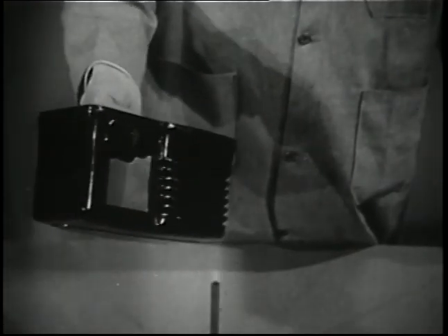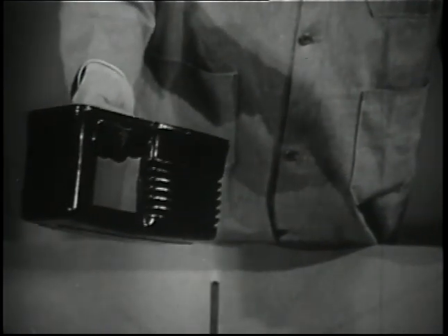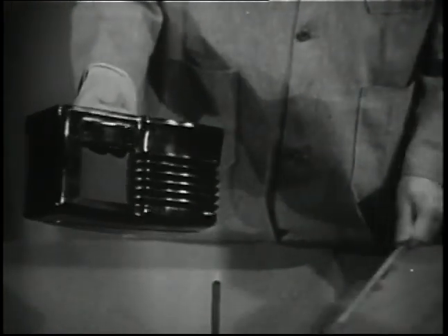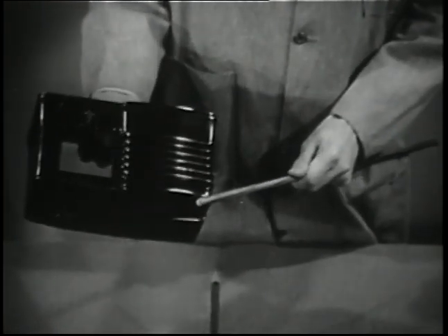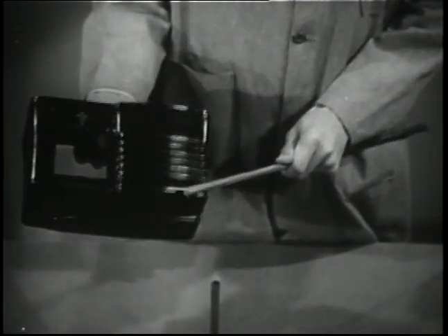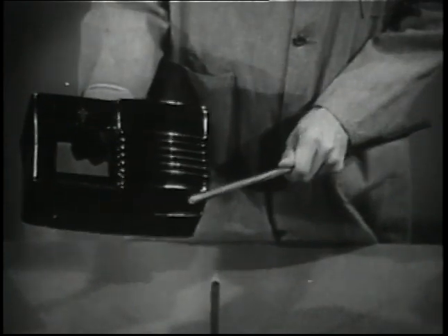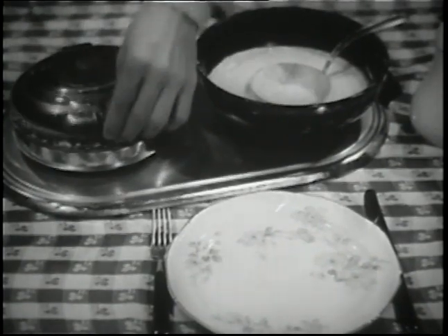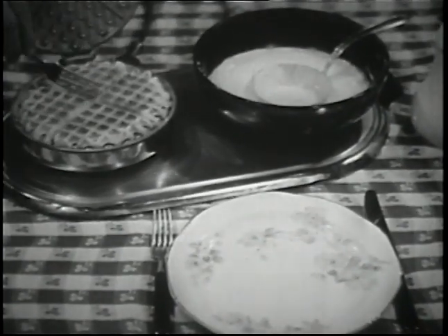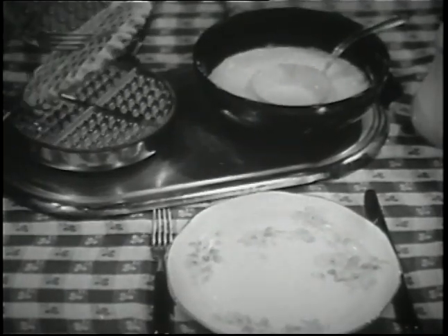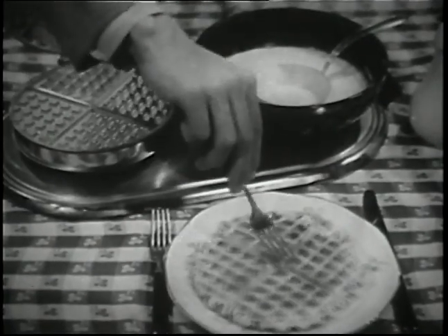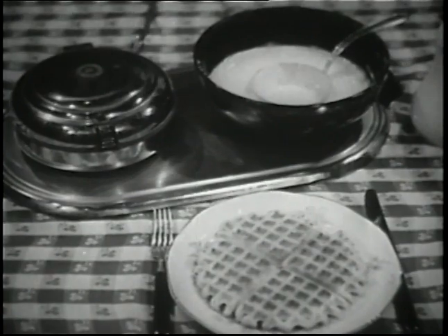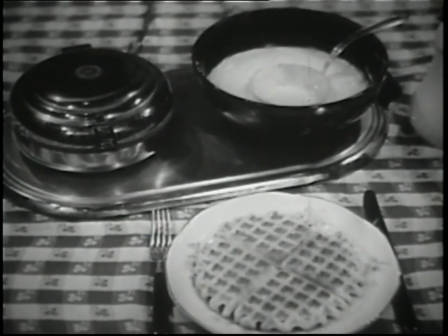A thermosetting material which hardened through chemical changes under heat remains as rigid as ever. It may char, but it cannot be softened or melted. Once formed and hardened, it can never be softened and reshaped. Thermosetting materials are hardened by a process that can be compared to the making of a waffle, which once it is set under heat cannot be melted or reshaped, so we call them thermosetting or hot set materials.